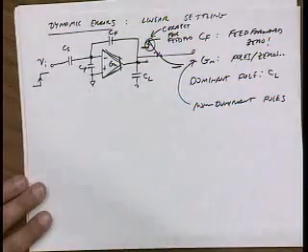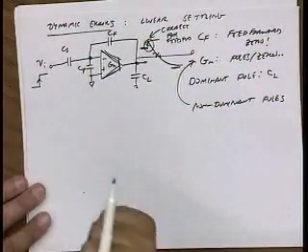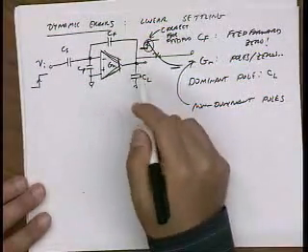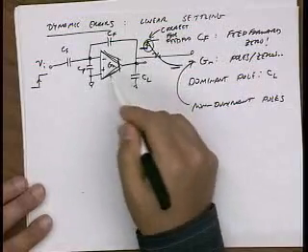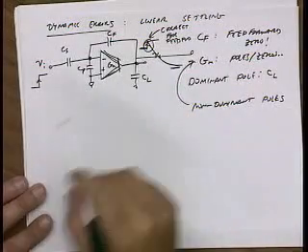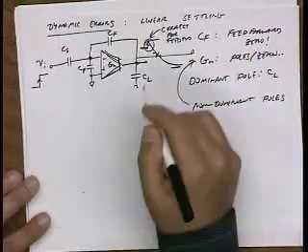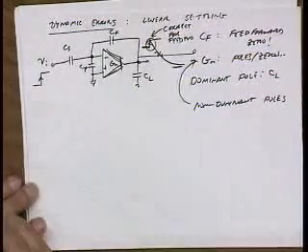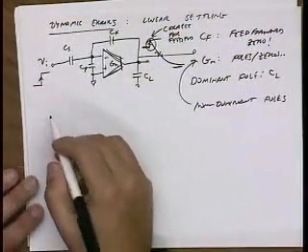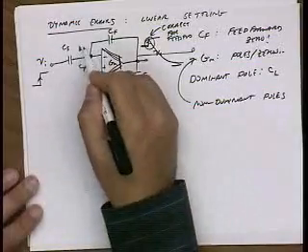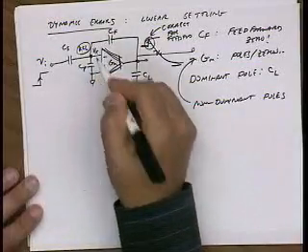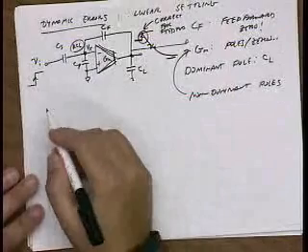So for that reason, and that reason alone, instead of just saying there's one pole GM over CL and then other poles and zeros are due to the GM, let's analyze this circuit carefully to find exactly the location of that pole and that 0. So again, I'm going to just write KCL here. Let's call this node Vx. In fact, we just wrote this equation.